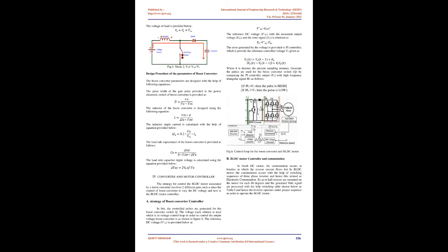It can be controlled with two methods: by controlling the DC supply voltage, the speed can be controlled, or by using PWM control in 3-phase inverter operation. The inverter is used only for DC-AC conversion, thereby energizing the stator coils in an appropriate manner so that the BLDC motor will run smoothly. The Hall sensors are mounted on the motor and provide Hall signals, which in turn are converted to EMFs for each phase, and the switching of the inverter is done accordingly.